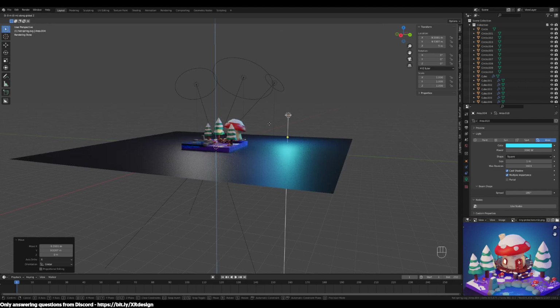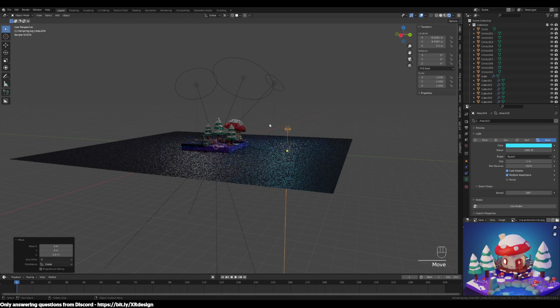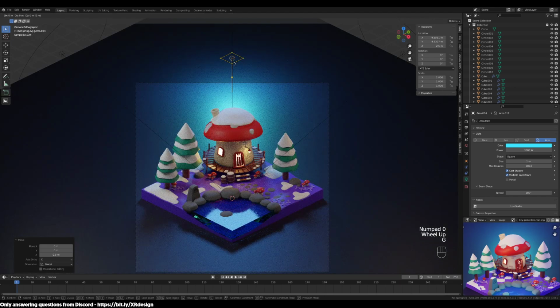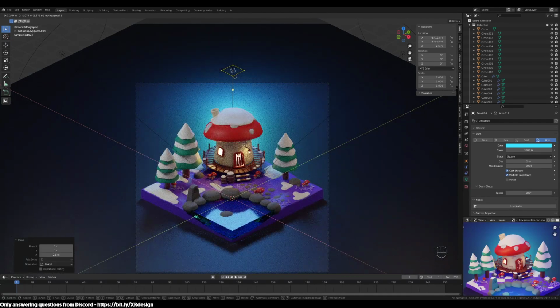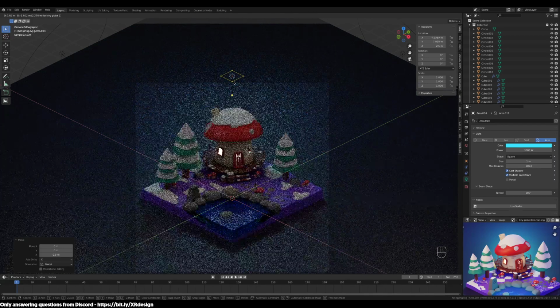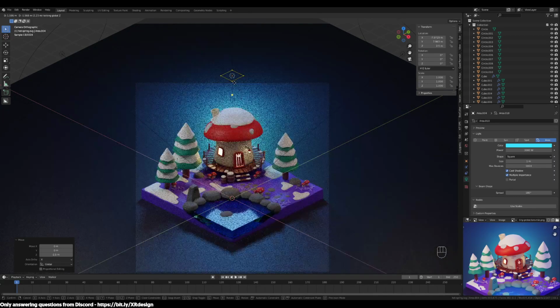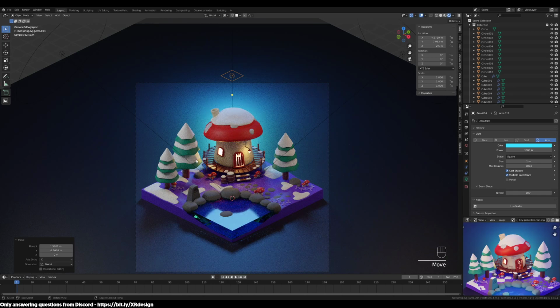We did 5 units above, so let's do 2.5 minus on the numpad and just half that height. And then from here, we're gonna move it along the horizontal again. Shift Z, and then just place it somewhere where it's emphasizing this object, this main house object.